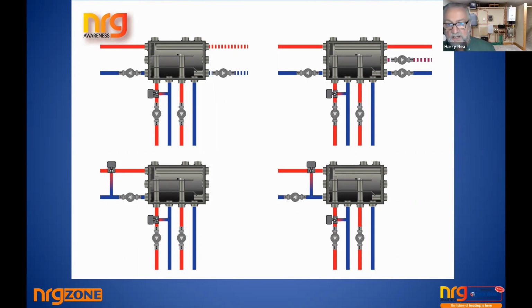You could have a boiler coming from the left and a zone on the right, or you could have a mixing valve feeding into the manifold, so that you would have high temperature over here. Then you can mix the whole manifold to a certain weather compensated level and still have a lesser mixing valve for, say, underfloor heating. And if your manifold is feeding out to another manifold, again, you can feed it on the way in or on the way out, so it makes no difference whatsoever.